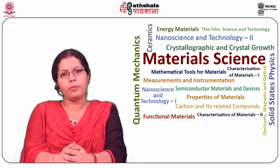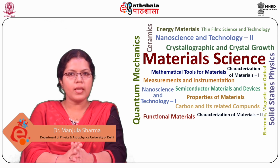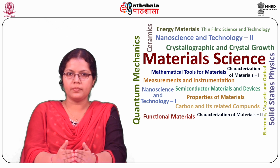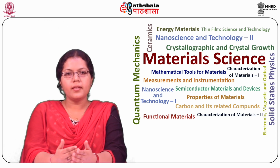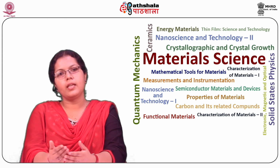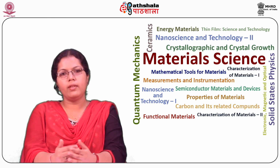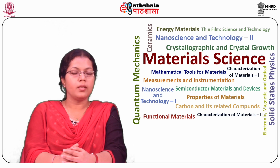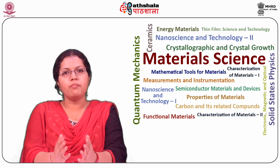The third main component discussed in this module is capacitors. Due to several factors, capacitors do not show perfect and constant capacitance at all frequencies. There are ohmic losses in the plates and connecting wires, interfacial polarization and power loss in dielectric, and several other factors. We studied that the dimensions of capacitance are those of length if the permittivity epsilon is taken as dimensionless. Therefore, values of primary standards of capacitance can be known by measuring lengths.